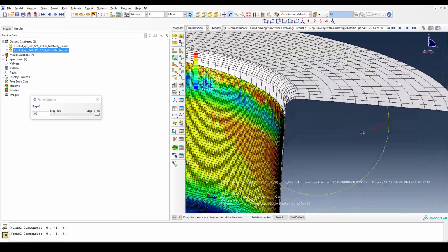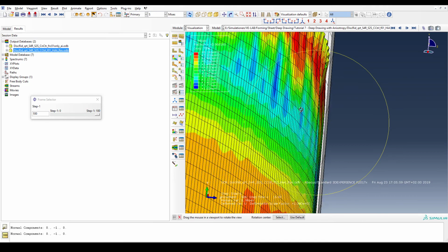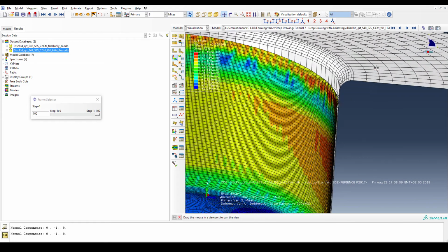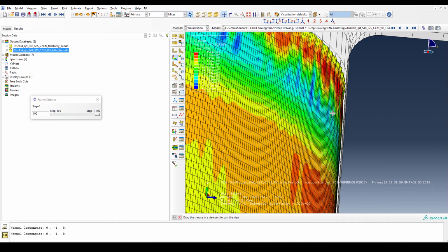However, the geometrical waviness is again also defined by the gap, the clearance that you leave between the punch and your die, right? If this is different compared to the distance you keep between the blank holder and the die, then the sheet will behave differently underneath the blank versus between the wall of the die, the wall of the matrix, and the punch, right? I think there was even a little bit more space here, so you have this added extra waviness even in this direction. So not just in this direction, but also in here.